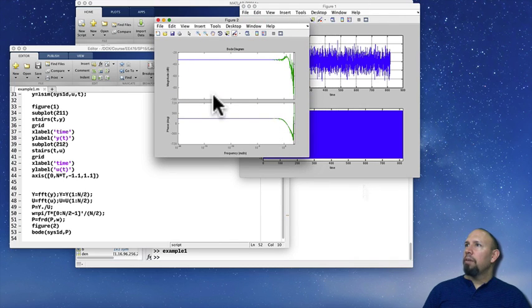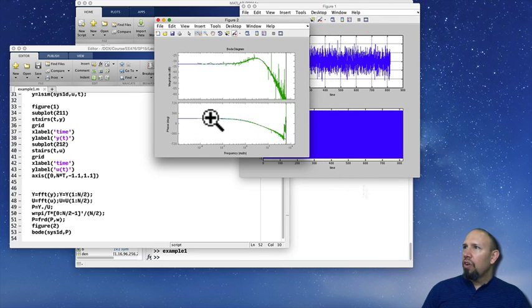And so we have the Bode plot. Now, our data is such that we get a lot of data at what looks like high frequency. And so I can compare the two. The green is the plot I got from the frequency response data. The blue is the Bode plot of sys1d.